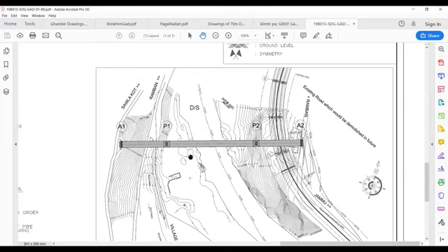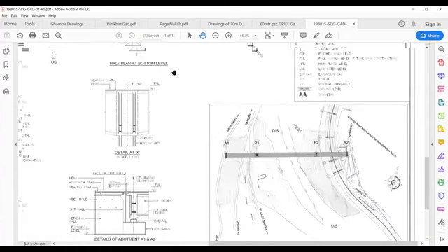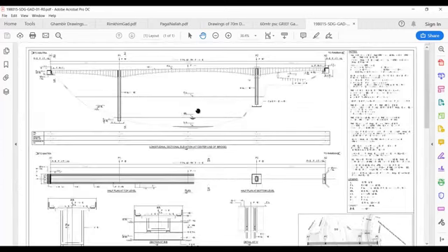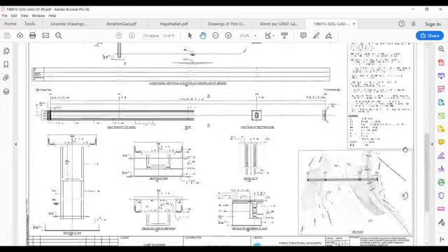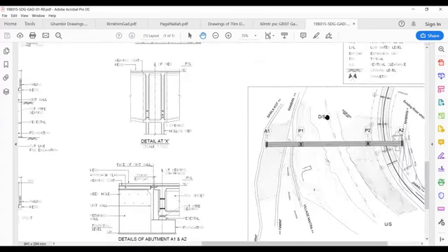Now we want to make this GAD of the bridge. GAD is the general plan of how the bridge would look. If I have to make the GAD, I have to show something on the left side and on the right side. A2 will be on the left, because if I stand here and look at the bridge, A2 will be on the left.